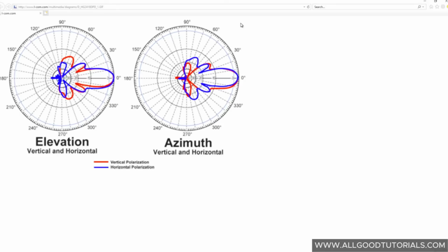And most of us think in the horizontal path because that's where we're thinking coverage. And most of us want to minimize the amount of radiation that we're sending in the vertical path, i.e. down towards the ground or up towards the floor above. And you can see that these antennas are pushing the energy in this direction. And so if you had a device that was in this direction, it's now going to be able to connect, but it is not pushing energy in this direction. So if you had a device here, it would no longer be able to connect. So these are highly directional antennas. Again, reinforcing that whenever you replace the antennas, you're going to impact where you have coverage, what devices can connect and what devices cannot connect. In Wi-Fi networks, you are not amplifying the signal, you're just changing where that energy is directed out and over the air.